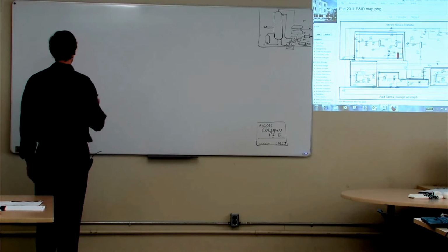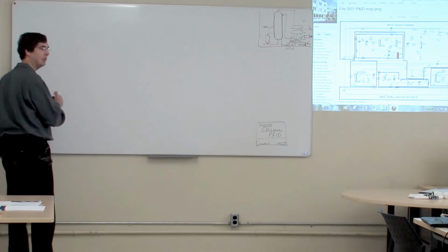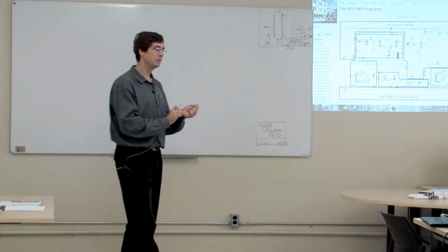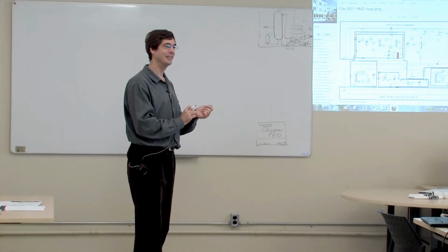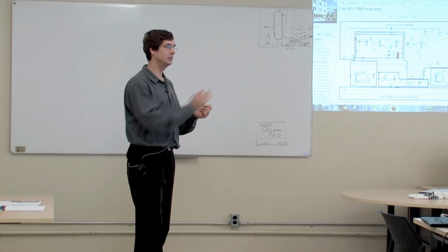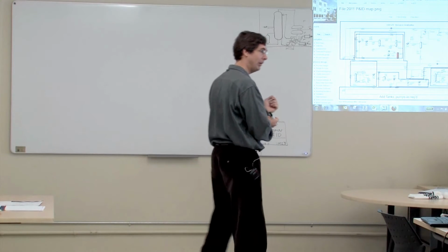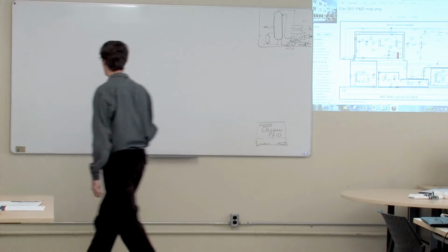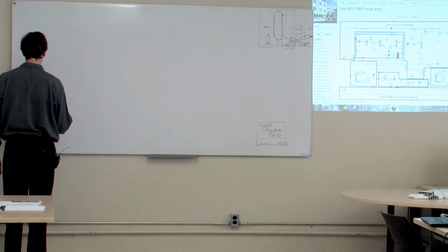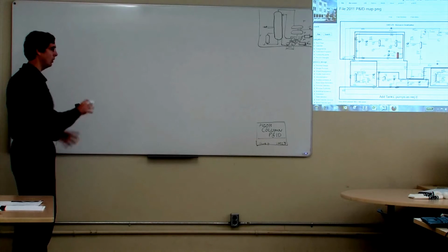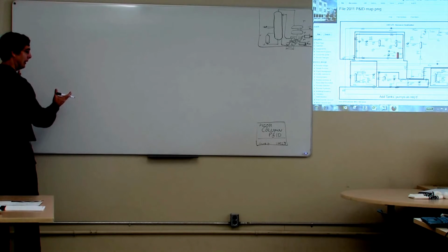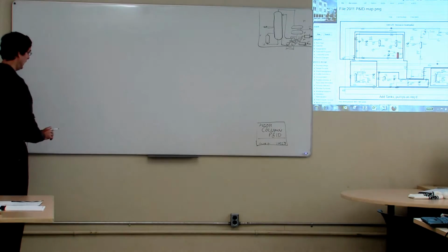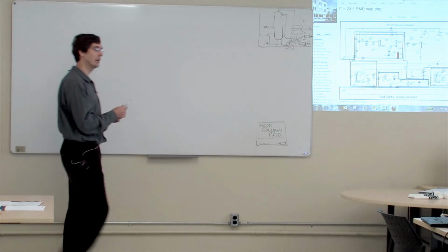So let's get my reboiler in here. What kind of reboiler did you guys use? Dave? Anybody? Anybody got their reboiler? You guys used a kettle reboiler? Okay, we could do a kettle reboiler. Okay, so I'm just thinking about the kettle reboiler. I want to bring the steam in from the left. So I'm going to flip the kettle reboiler around so it's kind of shown this way. Is that because of the area, or you just decided to use a kettle reboiler?